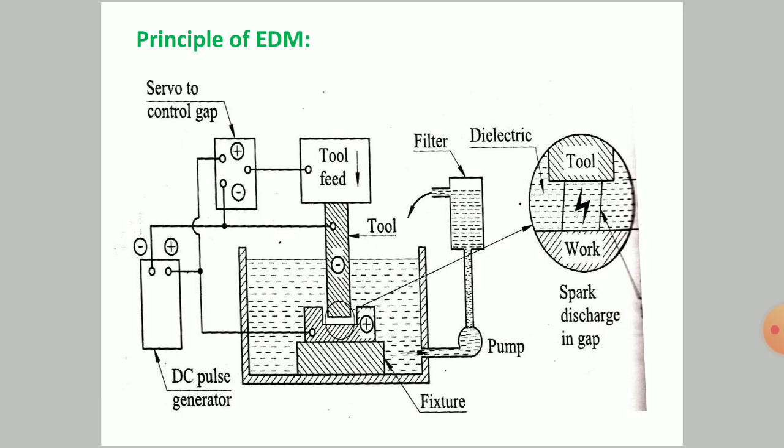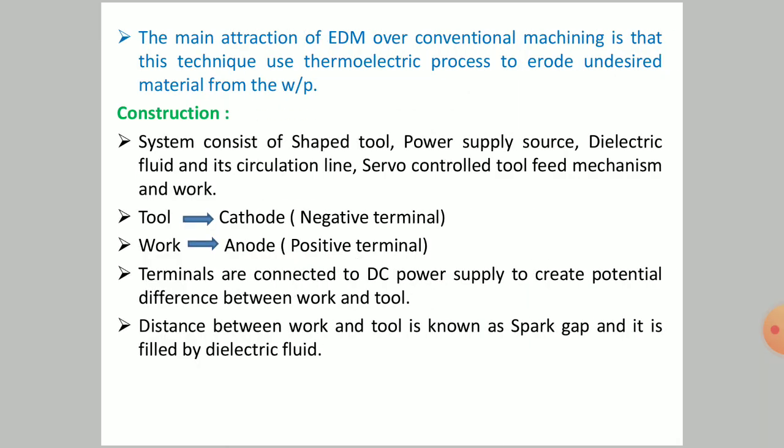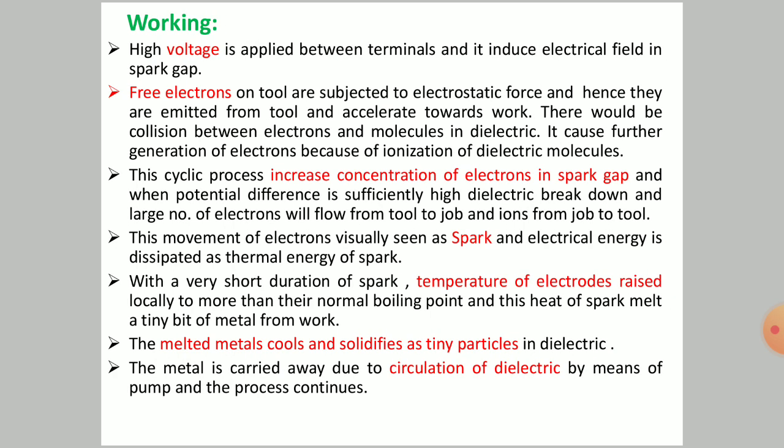The workpiece and tool both are immersed into the dielectric fluid, and the gap is maintained at around 0.02 to 0.4 mm. That signifies, that proves that the tool is not in contact with the workpiece. Now the working principle.